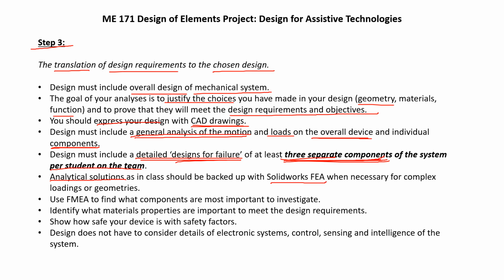Sometimes you may find, well, I really can't get as detailed with my analytical solutions, and I may have to make some big assumptions and simplifications when I'm doing out these hand solutions as compared to what I can do within a SOLIDWORKS FEA. And you may find out within the SOLIDWORKS FEA, some of these really detailed solutions, you're not quite sure if they're right. You might want to go back to that general hand solution you have and compare those two. So you're going to need the analytical solutions backed up with SOLIDWORKS FEA models as well. Now, one instance for these SOLIDWORKS FEA models, as I just mentioned, is when it gets complicated, for these complex, and what could be complex in terms of the loading and/or the geometries.